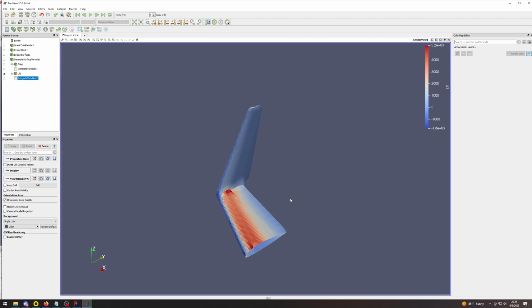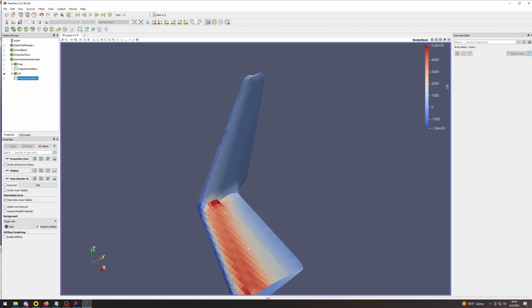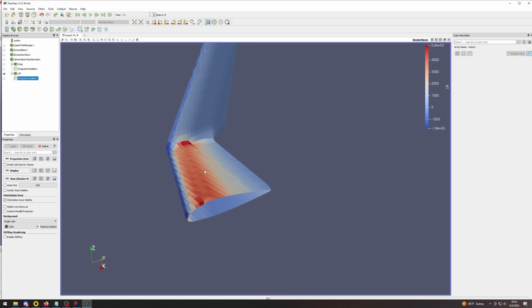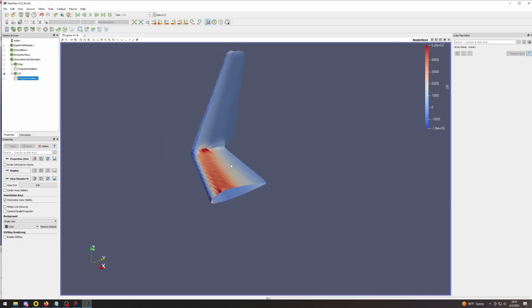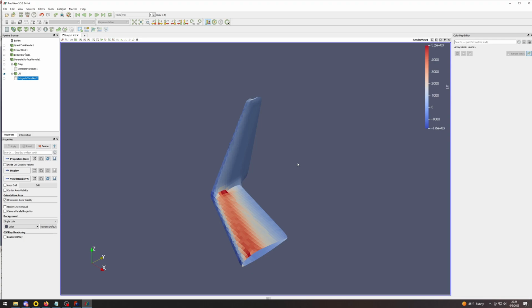Although those numbers of drag and lift don't mean a whole lot because we have such a granular, not smooth surface, the change in them from one curve of the wing to another, for analyzing the minor changes in an aircraft design, this is a great method, especially when you have those real world numbers like I did to compare them to.